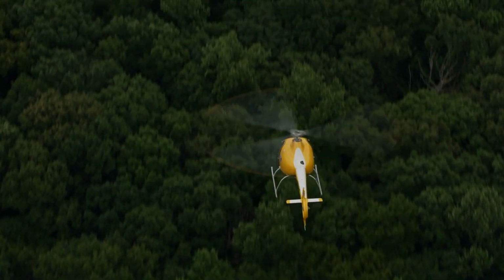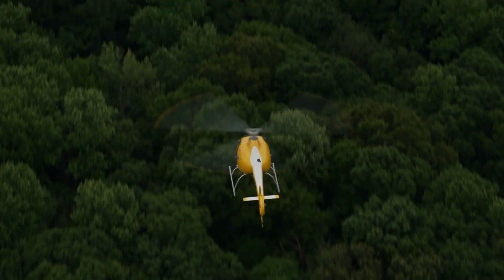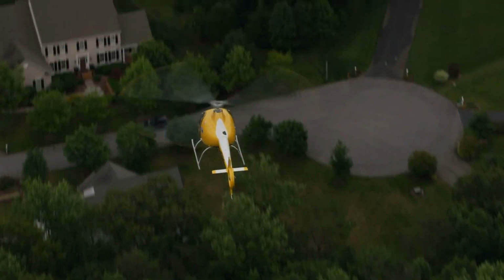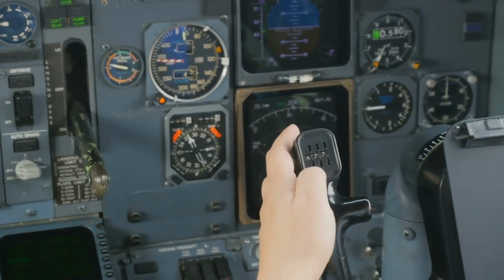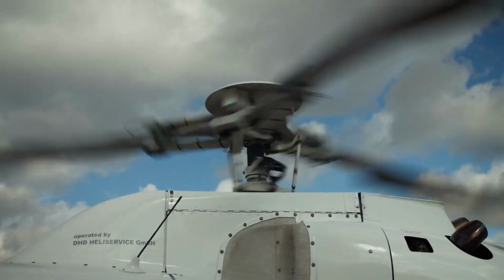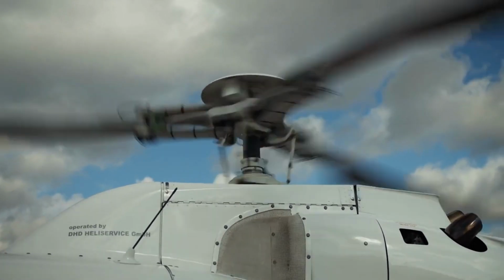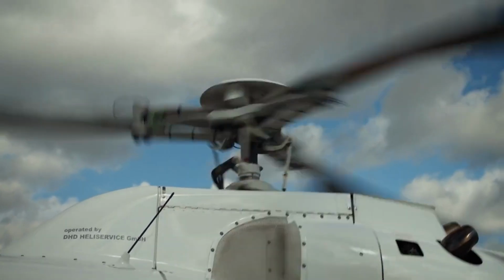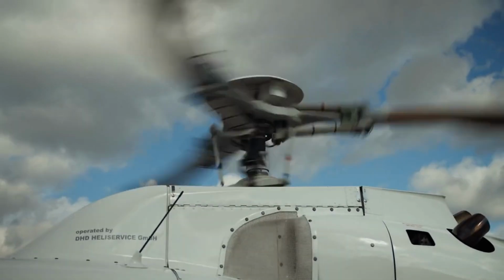To conclude the forward movement, the pilot applies a tender rearward pressure on the cyclic, bringing the helicopter to a gentle stop. The cyclic is then returned to neutral, preventing any rearward drift. Alternatively, forward motion can be stopped by gently applying rearward pressure to level the helicopter, allowing it to drift to a graceful stop.